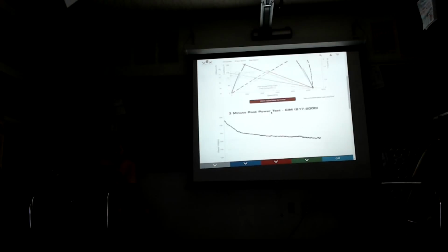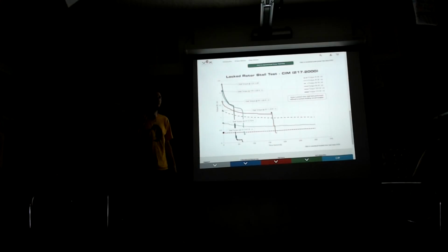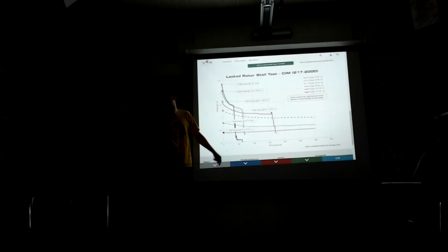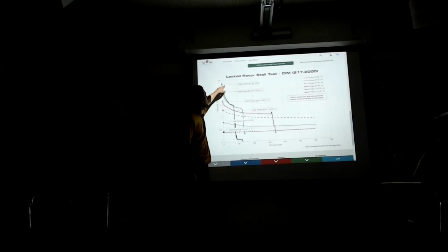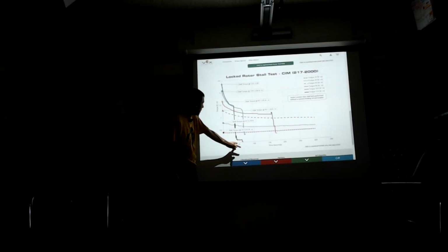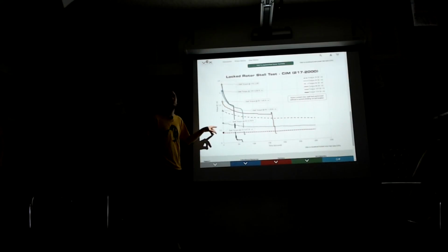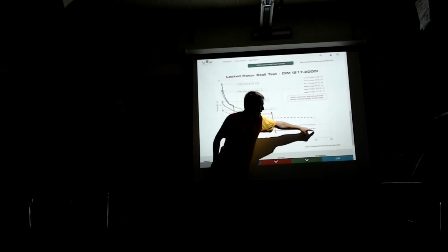One of my other favorite plots, which we use a huge amount, is the locked rotor test. Somebody tried 2 volts, 4 volts, 6 volts, 8 volts, 12 volts on a motor, stalled the output, and waited until smoke poured out. Smoke pours out right here. So this tells you how long your motor will survive as it warms up. If you apply 12 volts, your sim lasts 40 seconds. And then I'm told smoke comes pouring out the sides and they're never useful again, and the smell permeates the building for a while. On a sim, if you apply 2 volts, you're going to get bored.